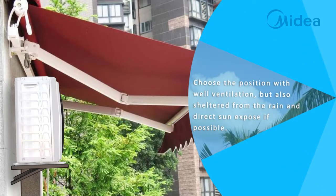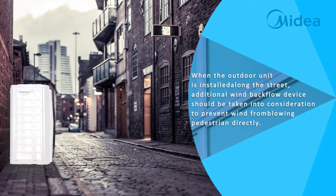Choose the position with good ventilation, but also sheltered from the rain and direct sun exposure if possible. When the outdoor unit is installed along the street, an additional wind backflow device should be taken into consideration to prevent wind from blowing on pedestrians directly.